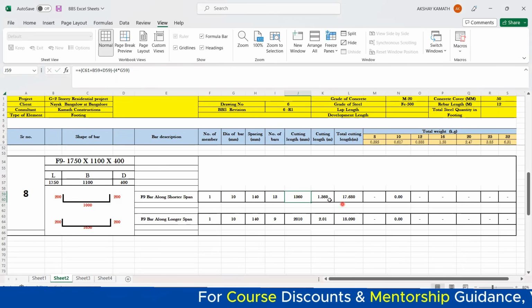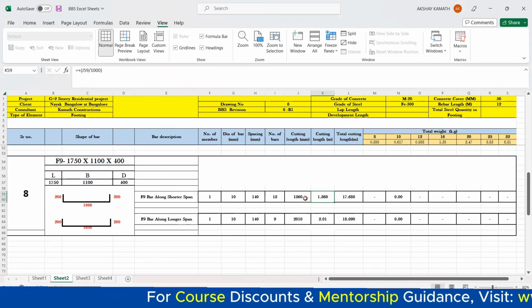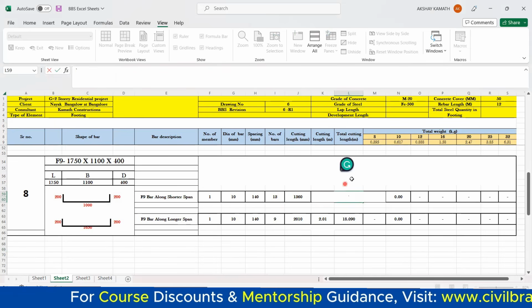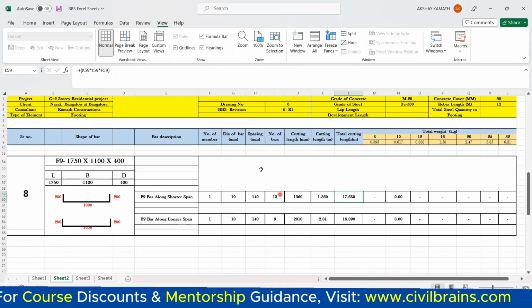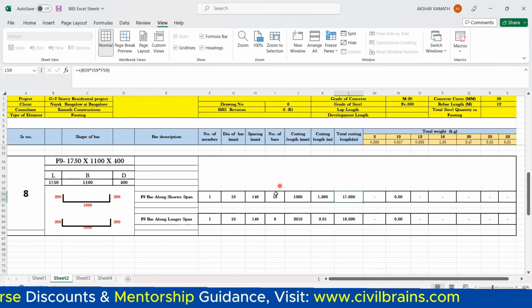Okay, that's it. So I'm getting 1360. The cutting length in meter will be 1360 divided by 1000, which is 1.360. Now come to the total cutting length. So total cutting length will be how much? Total cutting length will be cutting length of one bar, 1.360, multiply by number of bars and multiply by number of members, right? That is 1.360 into 13 into 1.